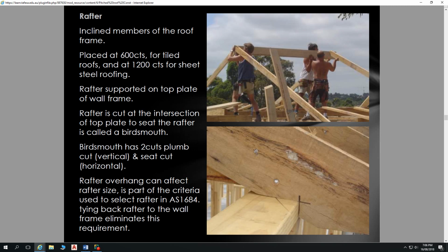Then those battens are tied to our rafters, so we can't pull those off with a strong wind. Then our rafters are tied down to our top plate using the strap. Then our top plate is tied down to our studs using that same strap. Then our studs are tied down to our bottom plate using that same strap.